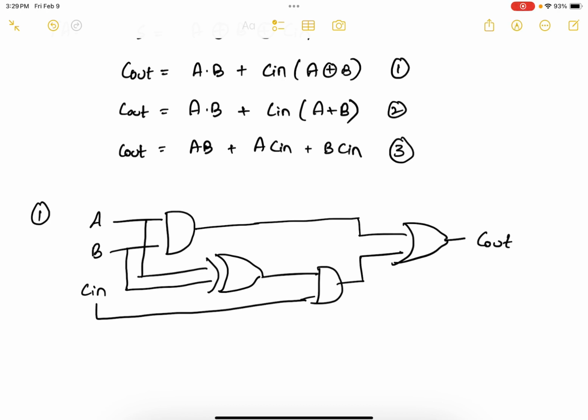As you can see, in this case, assuming that all gates have a gate delay of GD, the critical path of the circuit would be, so if you take the upper path, it's going to be this gate delay and this gate delay, but that's only two gate delays. If you take the lower path, it's going to be GD, one gate delay.